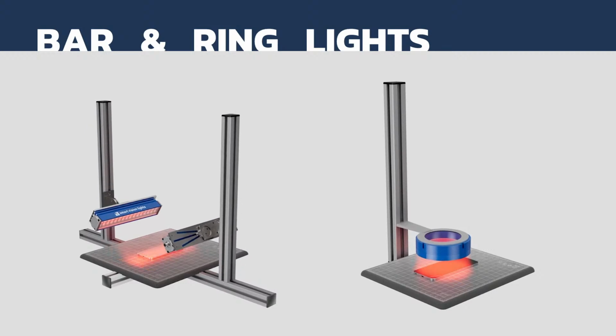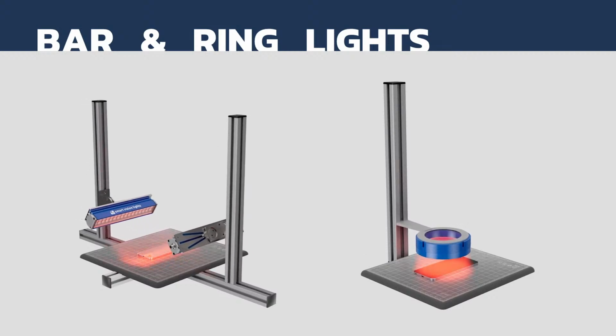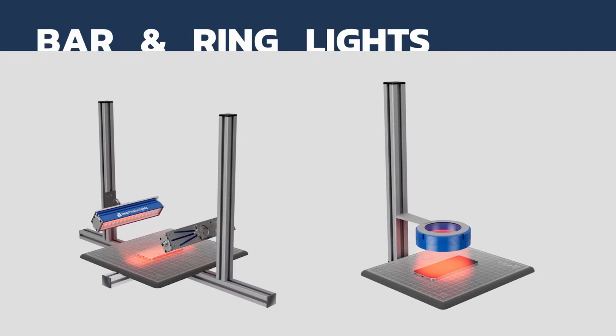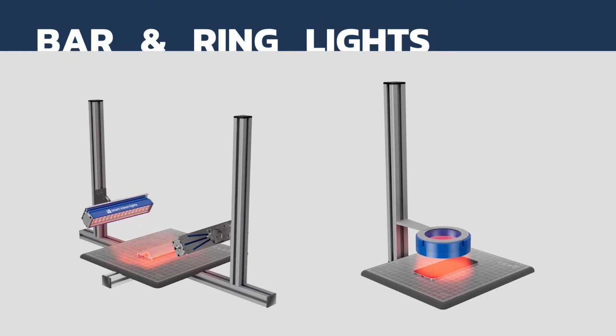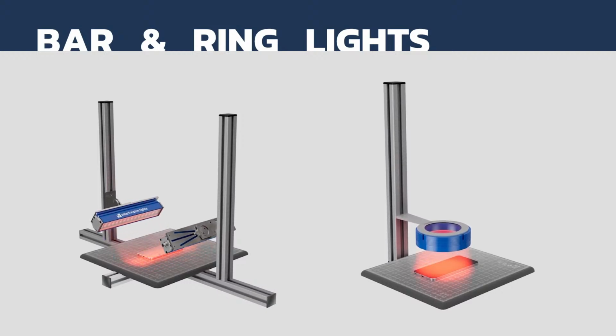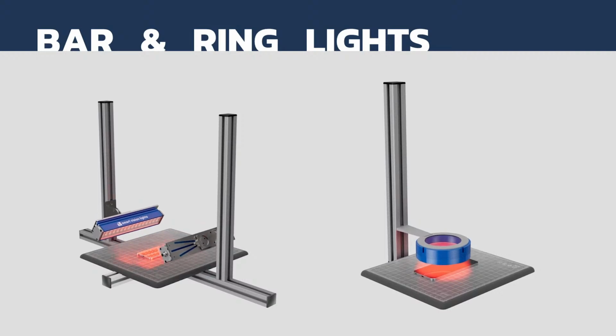So for dark field imaging, we're still going to use it in the same way, moving in the vertical z-axis, but to get a dark field effect with this kind of a ring light, we're going to have to keep it low and keep our working distances low. You might pull it back enough to get a combination. Sometimes we want a little bright field and start seeing that surface, but in general, you're going to keep it low.